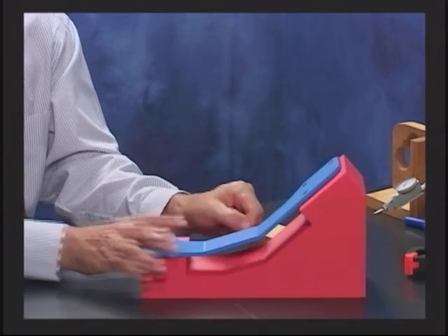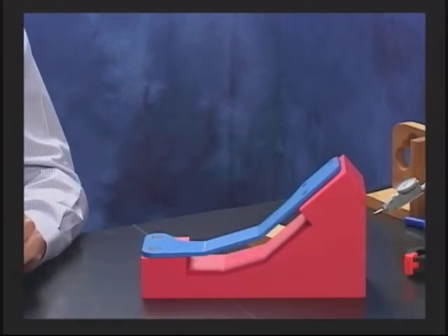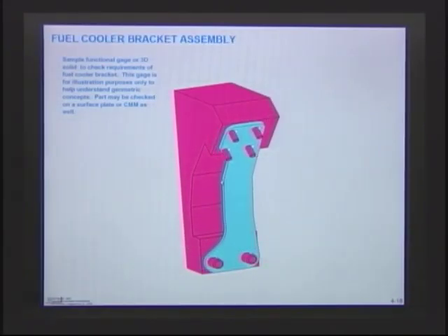And if you take a look back at our drawing, I'll show you the part actually animated a little bit in the gauge. There it is, and you can see when it moves around on the gauge, right? That would be the MMC. You notice the bottom holes there? You see that would be maximum material condition. You take a look at it, see it sitting on a gauge and see the holes as they got larger, they actually departed off a little bit, and that would be the maximum material condition. All right? So it gives you an idea what a gauge is, and maybe you see, we're getting right down to business. We're going after the most important things and telling you what's important here, what's important to us.